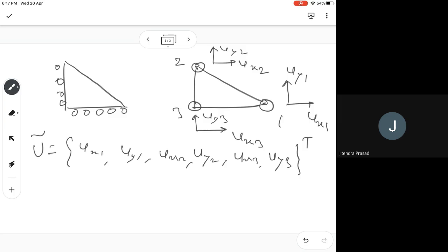And that means this will be equal to what? Look here, we are saying that this cannot go upward, so it can move because the roller is there. Roller is how we denote the constraint basically. What it means is that it cannot go up and down, but it can move this way.